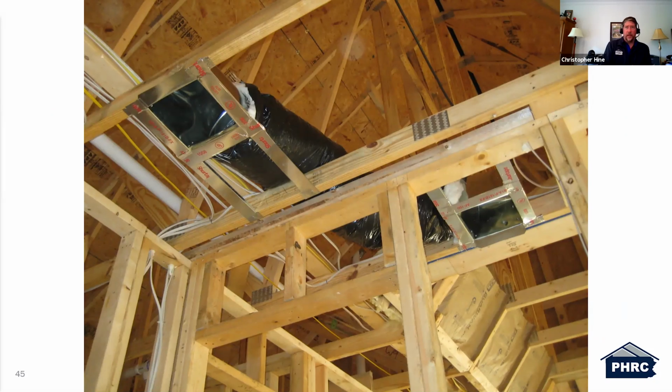But here's a picture of a jump duct going from a bedroom to a common area. This duct is not under pressure. So sometimes that is looked at as, wow, that'll be fine, right? But the only way a jump duct works is if there's a pressure difference. So this works when you do not have a dedicated return in a bedroom, the door is shut, and conditioned air is being supplied to that bedroom. This is a pressure relief for that room.